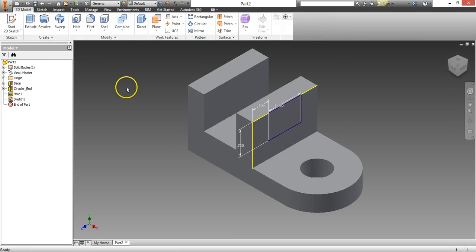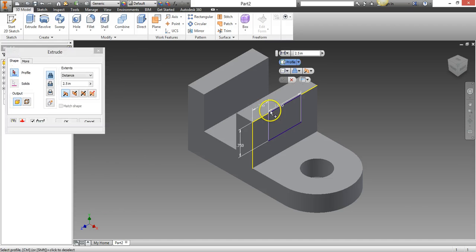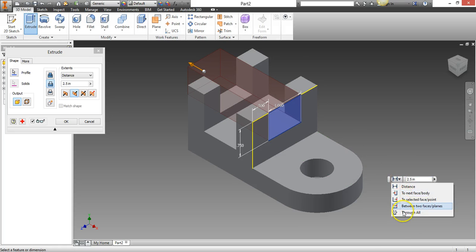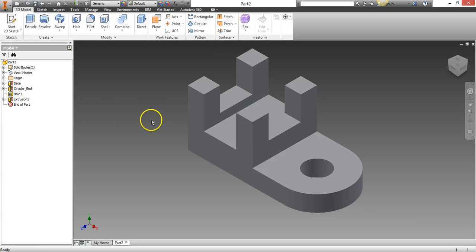And then I'm going to go ahead and extrude. So I need to select what I want to extrude, and I want to cut this, and I want to do through all. That way it goes through the entire shape. So we have that now as through all. I'm going to change this name and rename this RECT. That's rectangular cut. Click somewhere else.